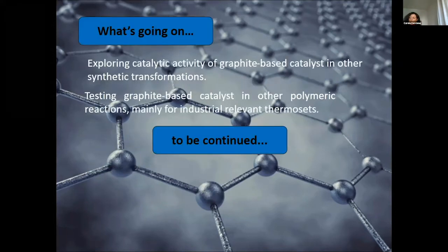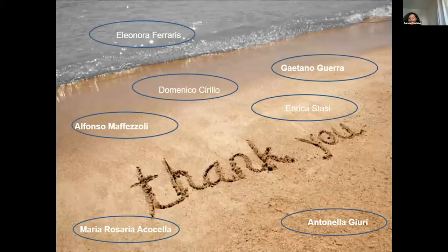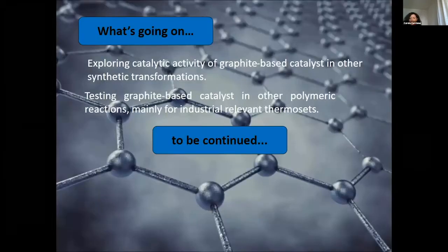So, in conclusion, we propose the double important role of the carbon ashes as a reinforcing filler and catalyst for cross-linking reaction of the epoxy resin with amines, and an innovative role as a filler, for example, in different kinds of applications, able to improve the mechanical properties of the cured systems. So the work needs to be continued, I know.